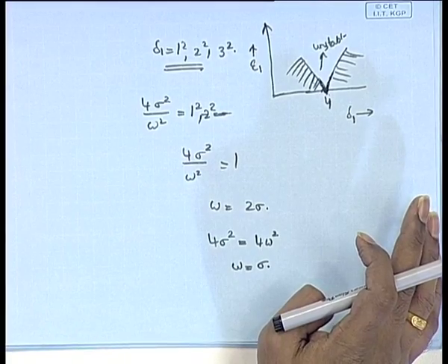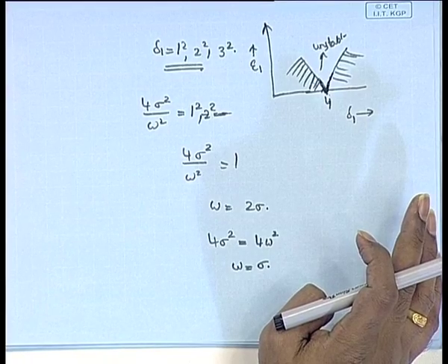When there is a relation between the wave frequency and the natural frequency of oscillation of the ship, let us consider heel, if they are equal, or if they are in some ratio, then you will end up with parametric resonance, a region with very high vibration, where phi becomes unstable or goes into a capsizing mode. So, these are different types of parametric resonance that you come across in ships.